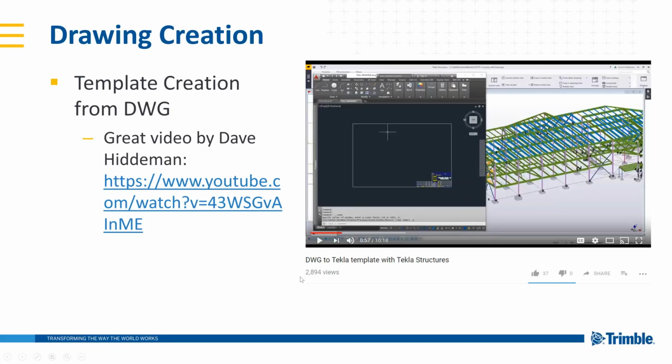This goes through the process of bringing in a DWG file that is your template, your title block, bringing that into the template editor, adding in the intelligent value field so that anytime your project name or your project address or one of the subcontractors on the project, anytime any of their details get updated, it doesn't need to be manually updated on every single sheet. You just do it in one place and all of your sheets will get updated. All of that information is included in this video. So go check out this video on YouTube to learn more about creating those title blocks.